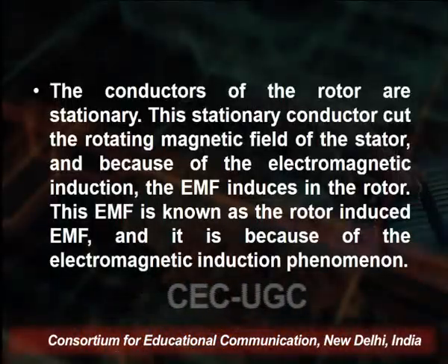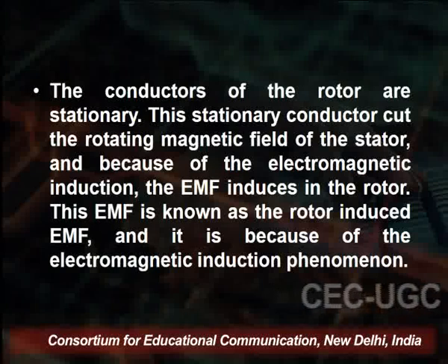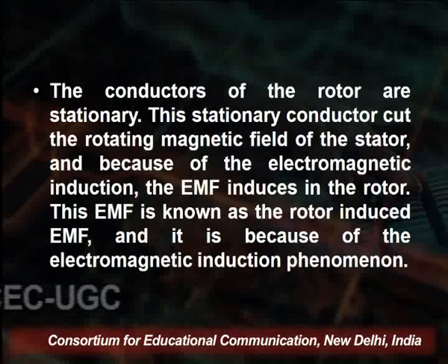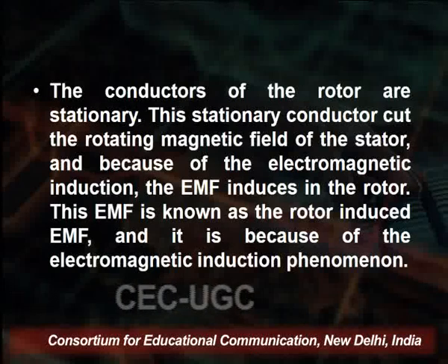Conductors of the rotor are stationary. These stationary conductors cut the rotating magnetic field of the stator. Because of electromagnetic induction, an EMF is induced in the rotor, and this EMF is known as the rotor induced EMF. This is because of the electromagnetic induction phenomenon. The direction of the electromagnetic torque and the rotating magnetic field is the same. Hence the rotor starts rotating in the same direction as that of the rotating magnetic field.